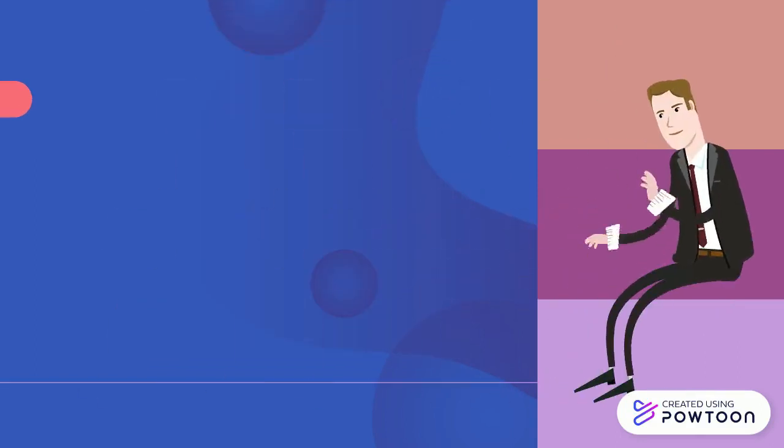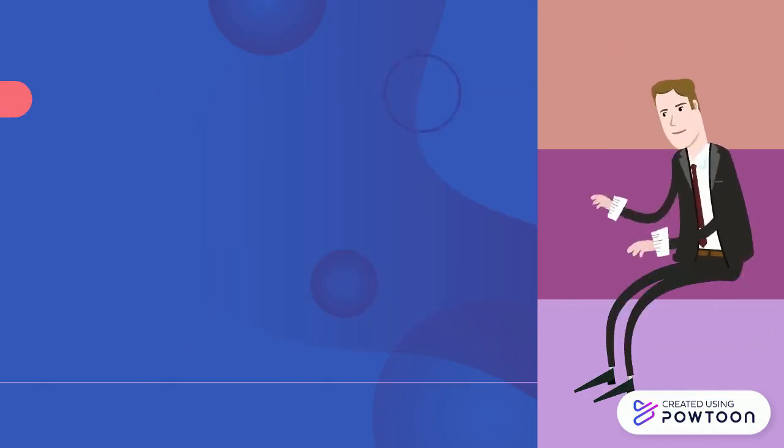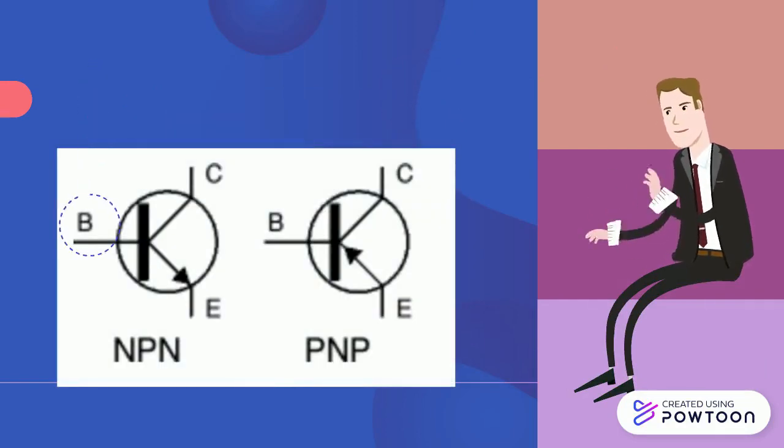Because it can function as an electrical switch, it can be used in systems that respond to outside stimuli. One good example of this is in motion sensors. When motion is detected, the detector outputs a current to the base terminal of the transistor, thus turning on the transistor and allowing current to flow from the emitter to the collector or vice versa.